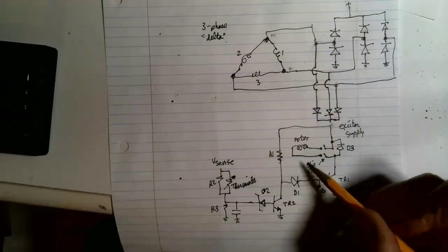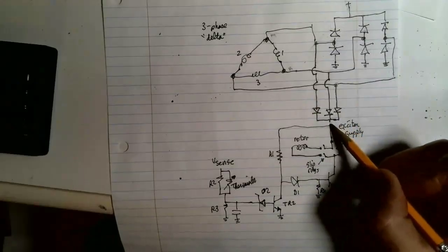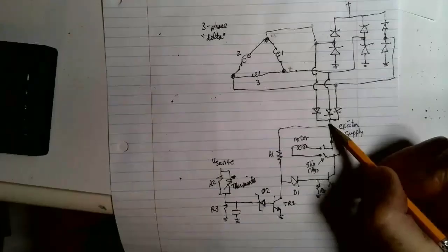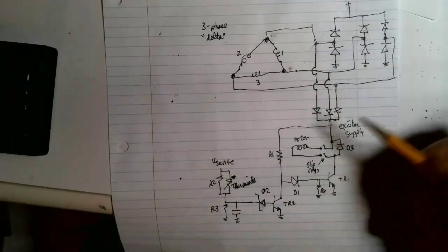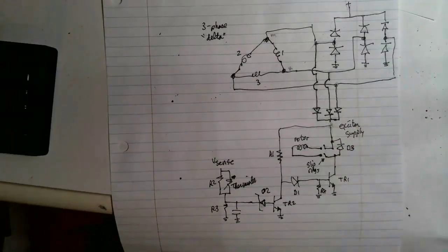And then as soon as the alternator starts working, and when you start the engine up, this potential comes up, the battery potential, and the generator light goes out. So that's how that works.